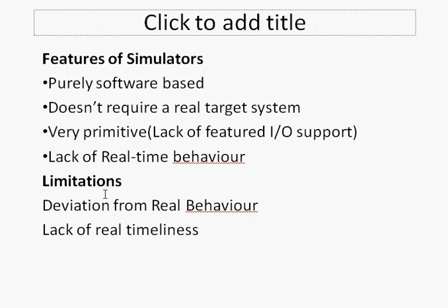Another limitation of a simulator is that it deviates from real behavior, because sometimes the clock frequency chosen for your simulator would be different from the clock frequency in your real working environment. In that case, the code might run very quickly and may not give you the correct result, so the delay may have to be changed. You might have observed this scenario if you have used Proteus.